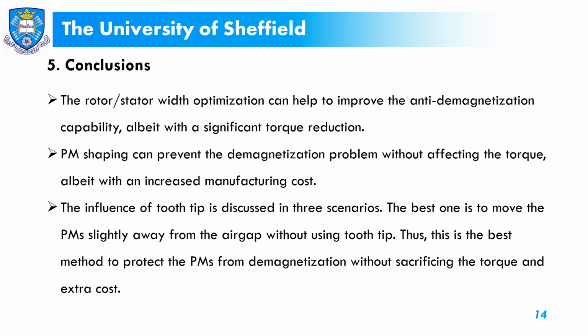Some conclusions can be drawn. The rotor-stator tooth width optimization can help to improve the anti-demagnetization capability, albeit with a significant torque reduction. PM shape can prevent the demagnetization problem without affecting the torque. However, the manufacturing cost is increased.